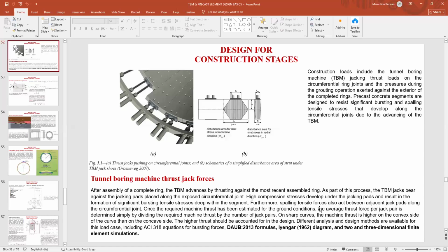In the segment design, apart from the structural design, the designer has to specify the fire design, and another thing is durability. That is the durability report, which is very detailed. He provides how the 100-year or 120-year design life is ensured based on the groundwater characteristics, and also the mix design that the contractor specifies: the minimum cement content, the minimum compressive strength, and the exposure class. All these inputs he runs through the standard software, and he demonstrates that the design life is more than 120 years.